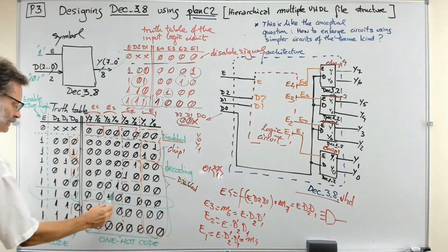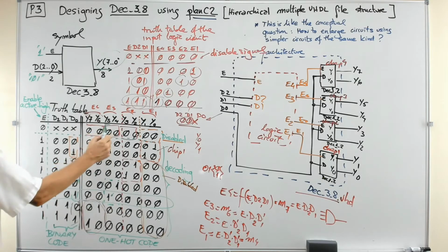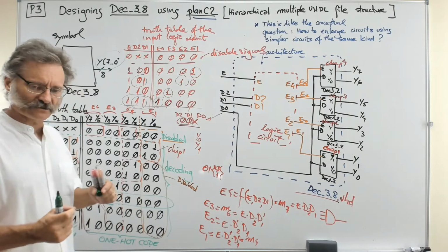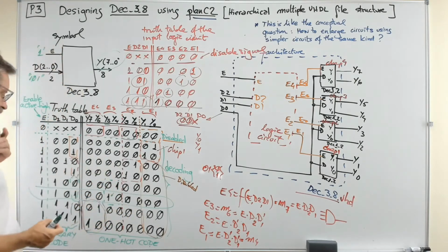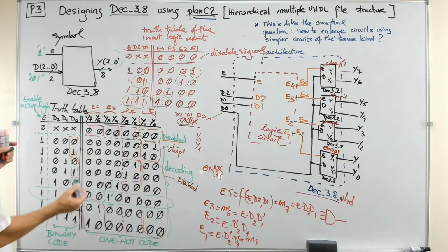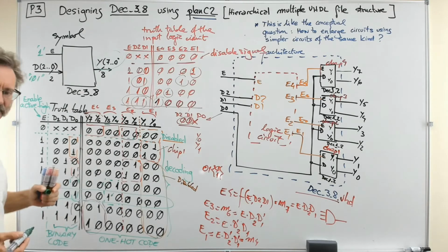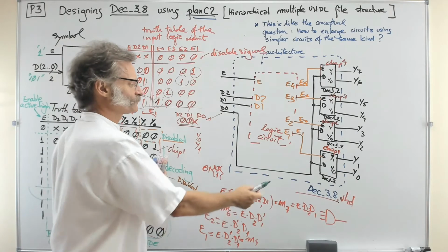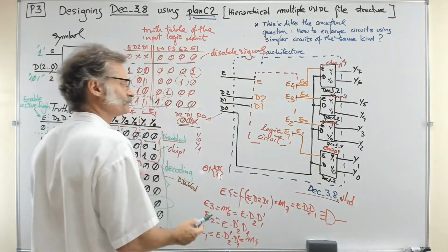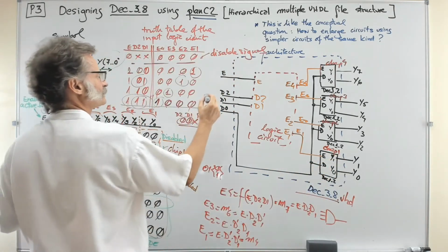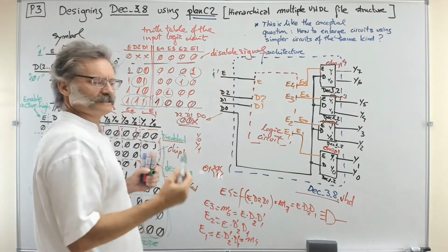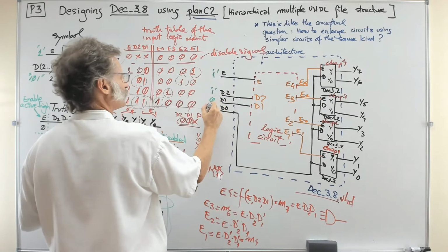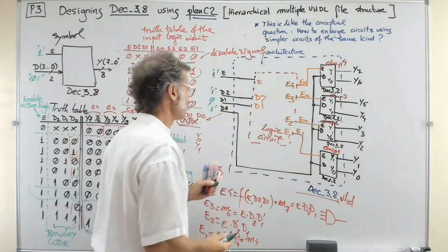Let's see if you have a 1 in the column Y5, keeping the others at 0, that is also very important. Let's see if this is true using this circuit that we have just invented now, because we have imposed the condition of using decoders 1 to 2. So this is what I would like to do, test these stimulus, 1, 0 and 1 in this structure.